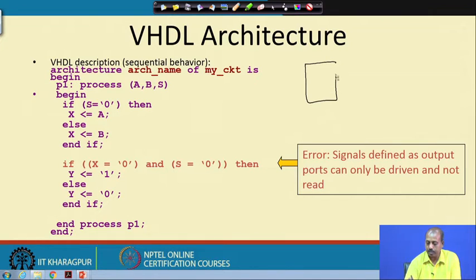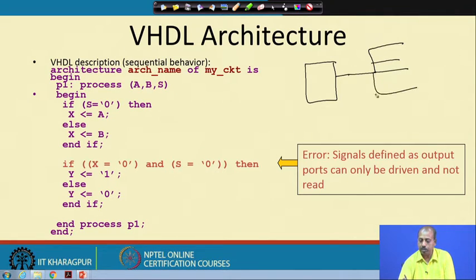and this is an output port. Now, suppose this point goes to 10 different places in my whole design. So, what will be the delay of this line, or whether you need a driver to be put here or not? That depends on the number of fan outs.